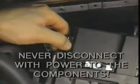Caution must be taken when testing the electronic components. Many of these devices can be damaged by voltage spikes and should never be disconnected with power to the component. The system operates on low voltages, and loose or misaligned electrical connections can result in excessive resistance and false readings.